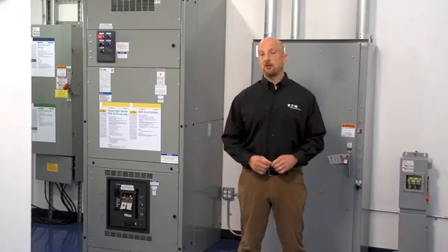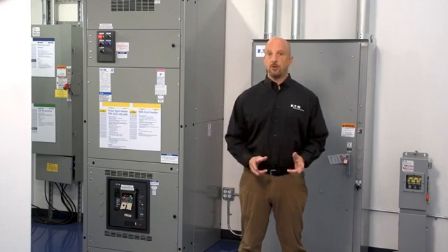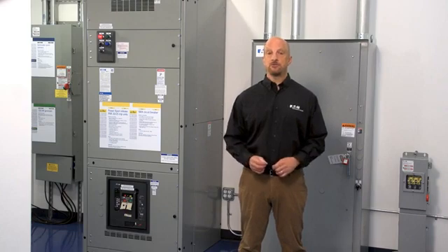Let's take a look at the components that make up typical circuit breakers. Here are the major components of a miniature circuit breaker. Notice the main components are the contacts, stabs, a handle mechanism, arc chutes, and more advanced ones have a circuit board with CTs. Here's a basic diagram of a molded case circuit breaker. These MCCBs have 5 basic components: an operating mechanism, arc extinguishers, contacts, a trip unit, and the breaker frame.